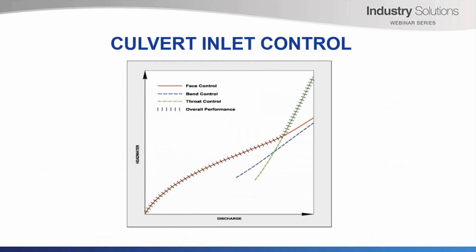Now, they didn't want their troop transports and their temporary runway network to become unpassable due to hydraulic failures, and so with an open checkbook, they took to researching culvert flow and developed physical models, some of them full scale, for 60-odd inlet configurations, and came up with empirical nomographs and later on equations, and published a design procedure for highway cross drainage, which is what we've used here, the FHWA HDS5, Hydraulic Design of Highway Culverts.